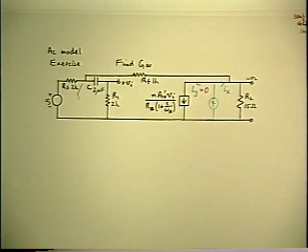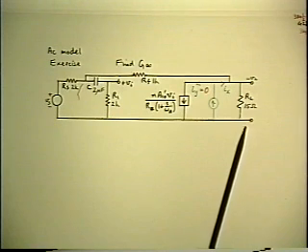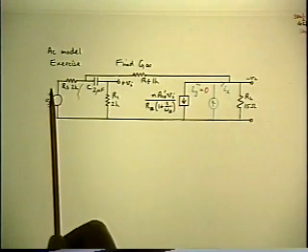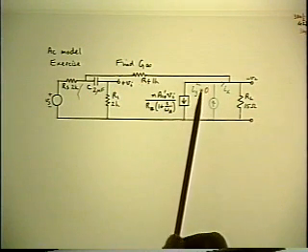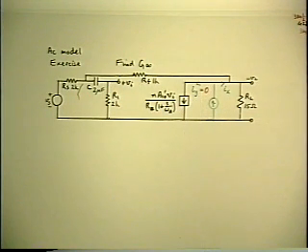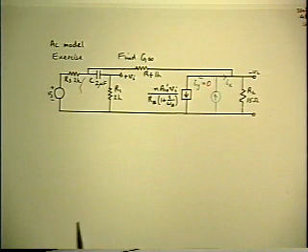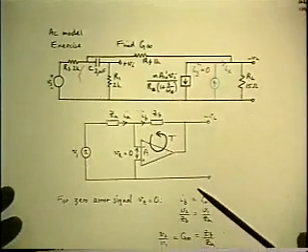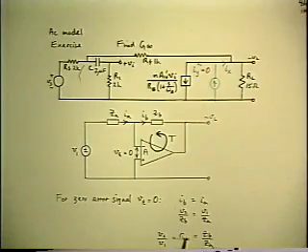And here's your chance to practice doing a null double injection calculation again. What is it you want to find out? You want to find VL over VS under the condition that IY is nulled. The key to doing this in what looks like a different sort of circuit is simply to recognize that it's the identical problem to this one that we've already gone through.